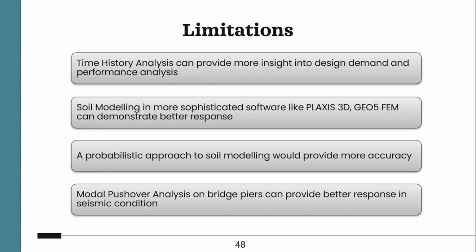There are some limitations to our study. First of all, while calculating the performance, we used pushover analysis, and during the pushover analysis some of the soils fail during the lateral loading. As a result, the hinge is not failing when the soil is failing, so some displacement is already occurring when there is no effect on the hinge.